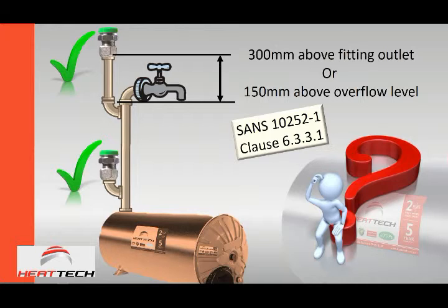It explains to you why you need it on the hot water side. Because, as Herman said, if you look at this tap, and if this tap was in a washing machine pipe or whatever it is, and the geyser got sucked out with hot water, and there was no vacuum breakers, this water would be sucked all the way into the geyser and down the pipe outside into the main water supply. And as Herman showed you in the beginning, you have a dirty amount of contamination into the water supply. So that's one of the main reasons why we do that.